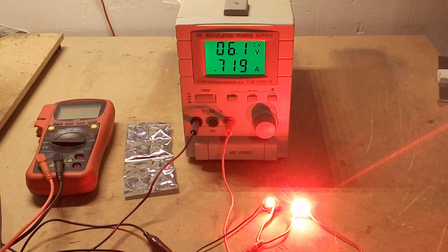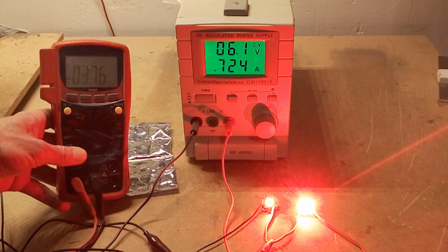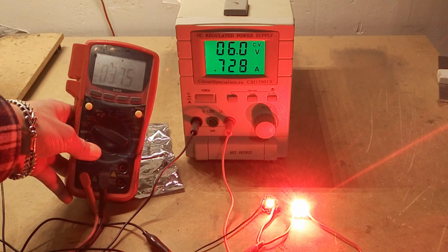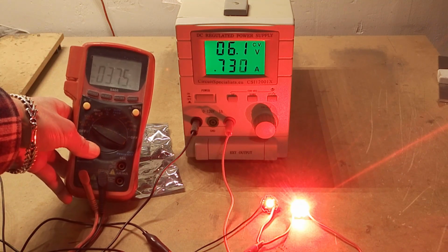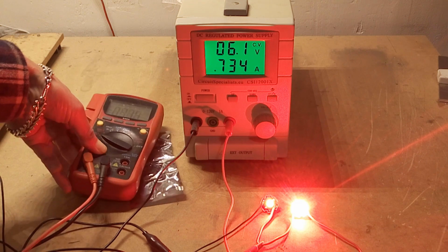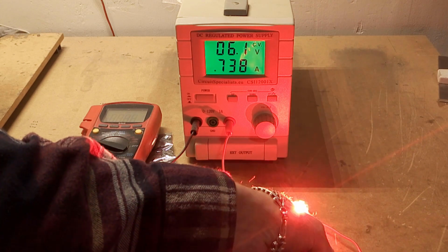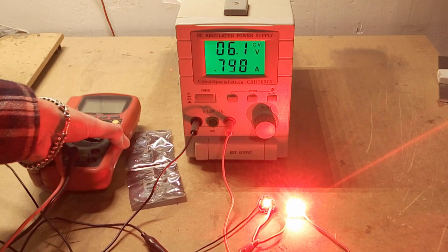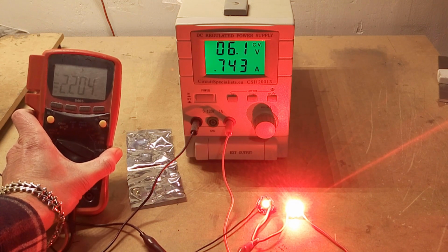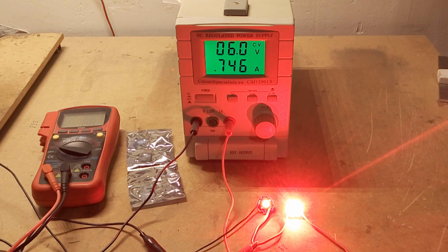Okay, now let's take a look and see how much each LED is taking of that 6 volts. Now here, I don't know if you can see it, you're getting 3.75 volts. That's off the Chinese one. Okay, now let's swap the wires across, hopefully without breaking the connection. Right, now we're looking at the high quality LED, and that is drawing, I don't know if you can see that there, 2.2 volts. So a massive, massive difference between the two LEDs.